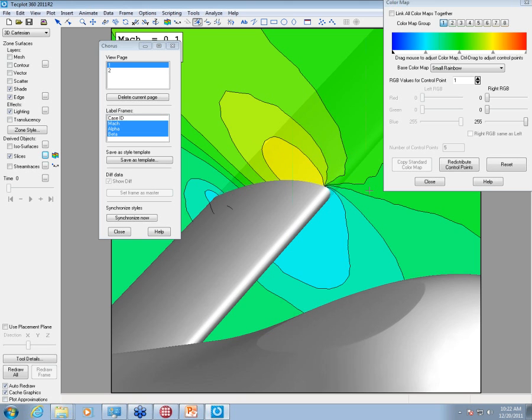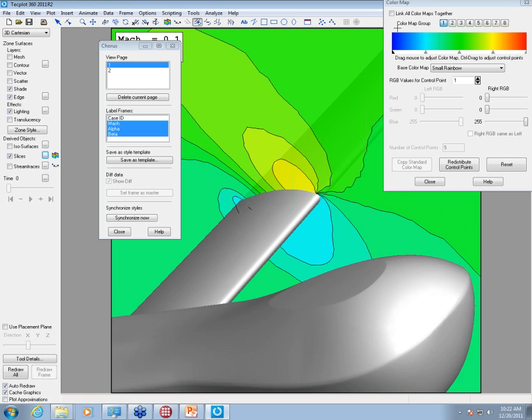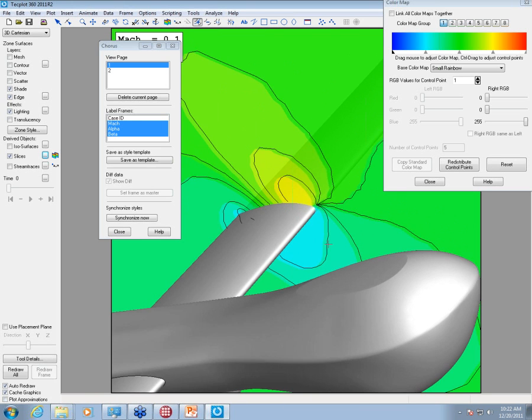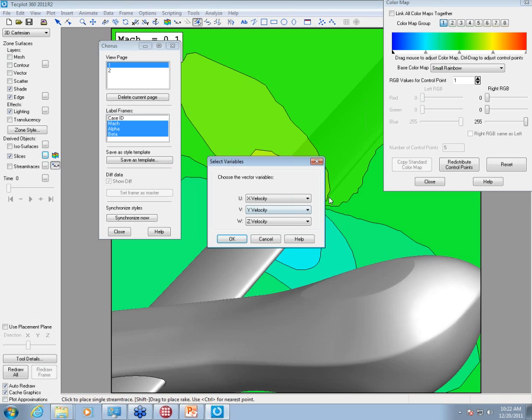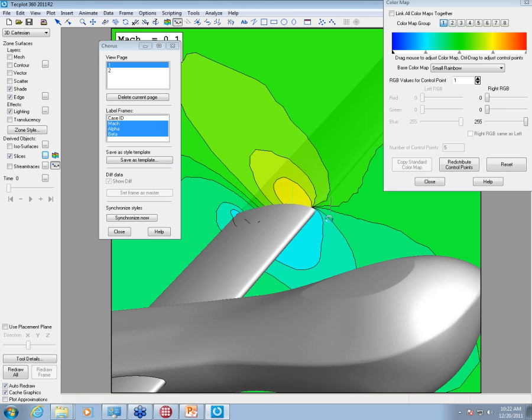So here we're going to look at some fine structure. I've just dropped in a slice. I'll zoom out a bit so we can see that. And one of the things I did was add some additional contour levels. So again, to see the variation in pressure coming off the wing, coming off the leading edge and trailing edge of the wing. And also for simplicity, I'm going to add, in this case, 10 stream traces, just to make sure that they look physically meaningful.